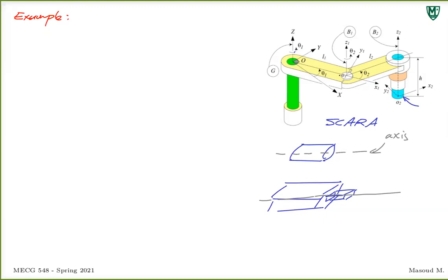Where is it with respect to this fixed area? Let's say this is fixed to some ground. So it's important to follow that. Important to have the position of this known at any given moment. Now let's see how we can transform the coordinates of that point, point O2, from the local coordinate frame it has, x2, y2, z2, to the fixed coordinate frame, x, y, z, the global coordinate frame.